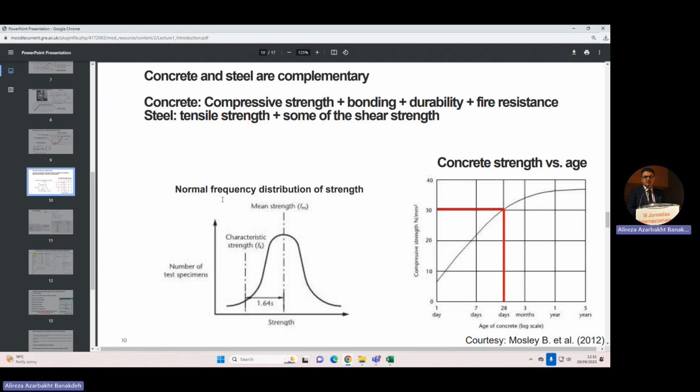It means that when we design for 30, it's a little bit more, and when it passes 28 days of life, it gets a little more strength, but we do not count on this part because we want to still have more safety factors. But do not rely on any concrete before 20 days. This is the daily life of the concrete. Here you have just poured it. It's not starting from zero, because 1 hour after pouring, it has some strength. So you don't need to wait a full day. After 1 or 2 hours, you have a minimum sort of strength.